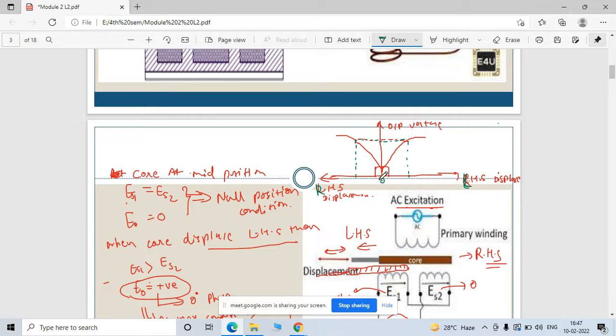I consider here the zero null location, the negative side on the left and the positive side on the right. So phi here is the 180 degree phase shift, denoted by the negative sign, and here phi is the 0 degree phase shift. This shaded, dotted region is denoted as the linear region, or linear range.